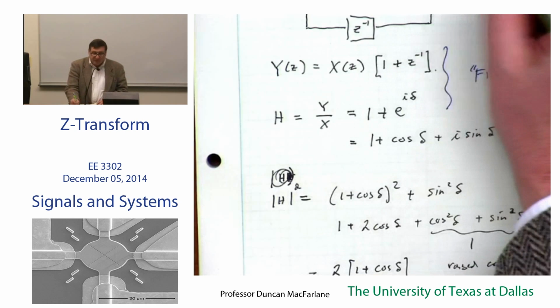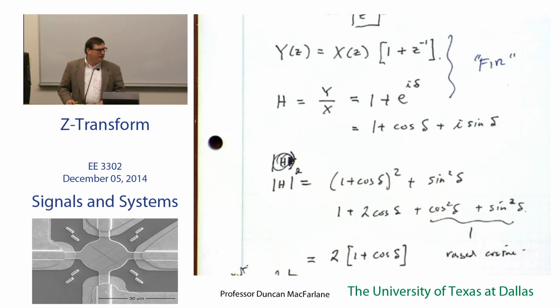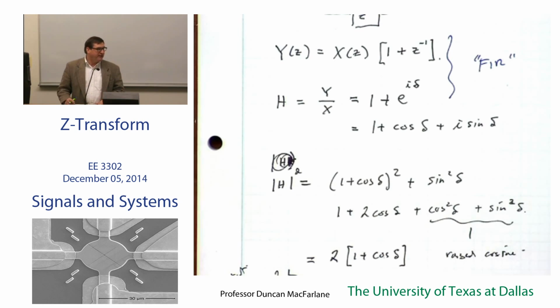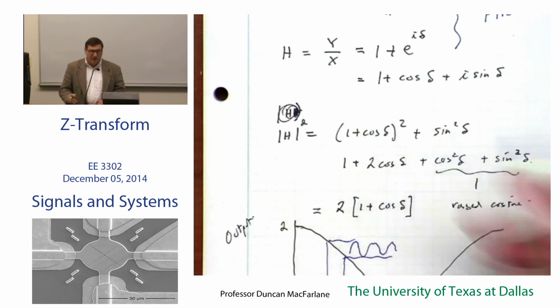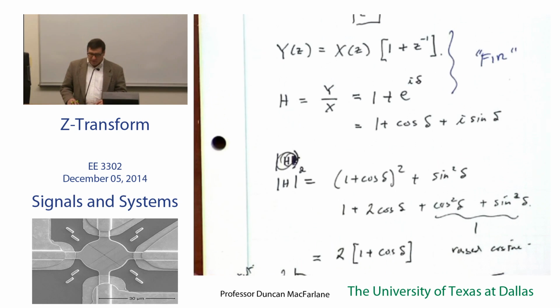So, in terms of this modulator, one more small comment about this. A couple lectures ago, I think, we talked about the modulation property, and people asked, how do you realize that multiplication block? Well, this nonlinear transformation is exactly one way of realizing that input-output multiplication. Okay, so in the optical world, you build a filter that looks like this. It can be operated as a multiplier or as a modulator.